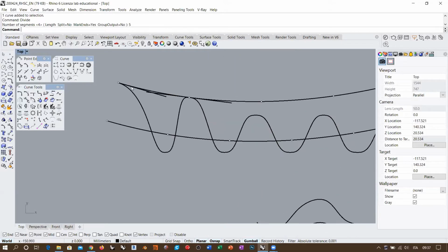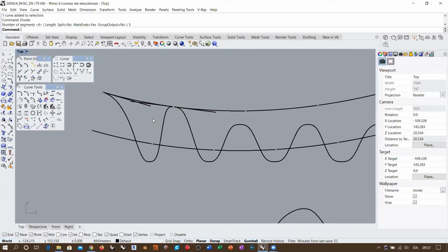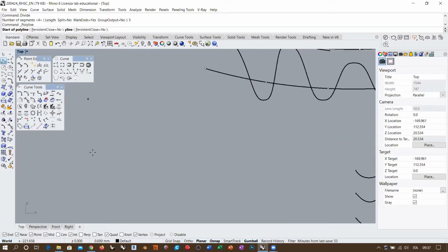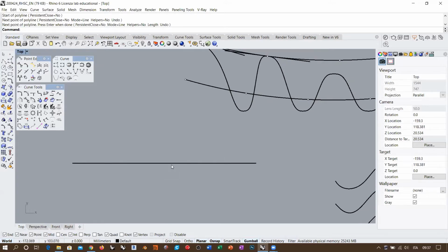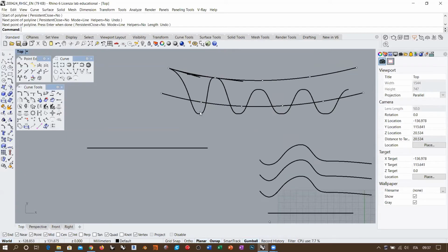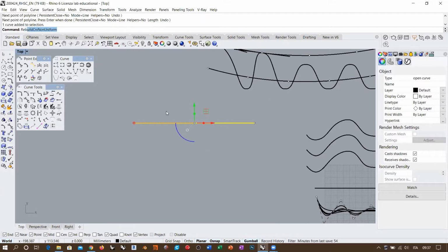Okay, I don't want to waste time with the definition of the amount of control points. I just need to take one line, and I need this line to have the possibility of being deformed in order to host 4 fingers and 5 mountains. Okay, so we know that 4 fingers means 12 control points. 3 of the 5 mountains means 9 control points. So it is 12 plus 9 is 21, plus 2 plus 2. So 25 control points. I take this one and rebuild it